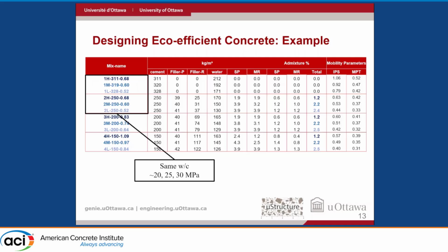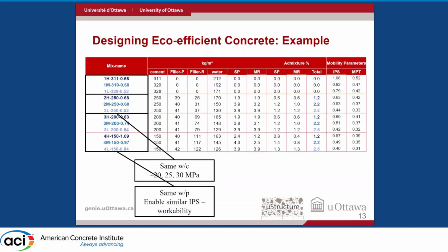So for this type of packed concrete with limestone fillers and so on, we can get performance with very different water to cement ratios. This is one of the discussions I was having with Mayra: once we prove that we can get performance out of it, there is a second battle, which is to be able to standardize those, because they're completely out of all of the standards existing in the world. But anyway, we tried to keep the same water cement ratio to fix the same microstructure, so that we can compare apples with apples. And another thing is that we tried to fix the same water to powder ratio, so that we could control the distance between the powder particles and then control workability in general.